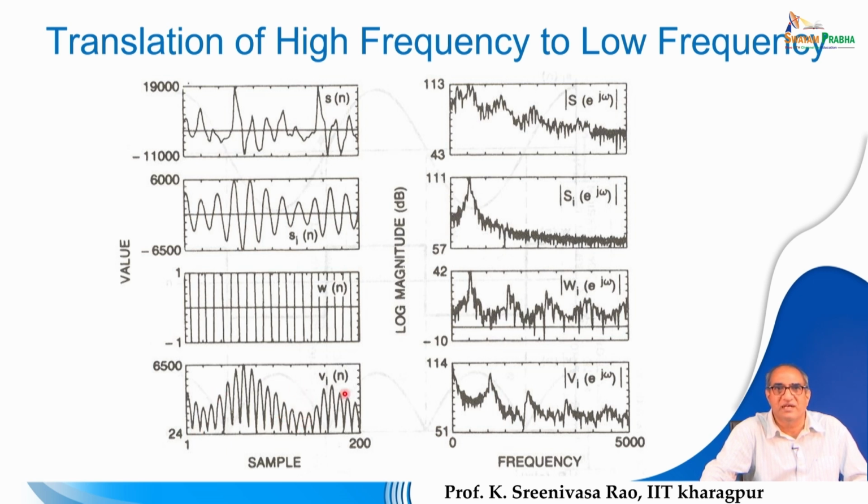Now if you analyze the rectified signal, you can see that whatever frequency band was there earlier will be shifted towards 0. This is the spectrum of this non-linearity. If you perform a convolution between these two, the spectrum of this nonlinear output will look this way. It means the information will be shifted very close to 0. Now if you pass this through a low pass filter, it will preserve the low frequency content up to this part and the remaining part will be removed.